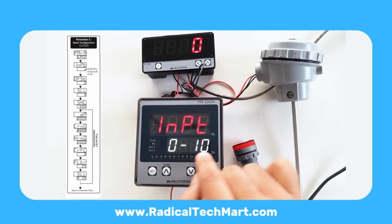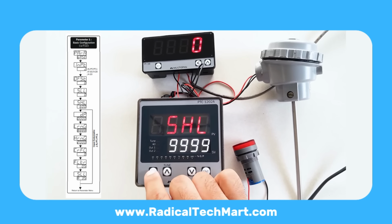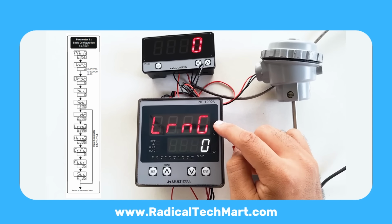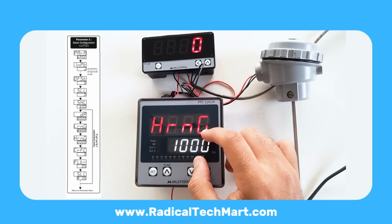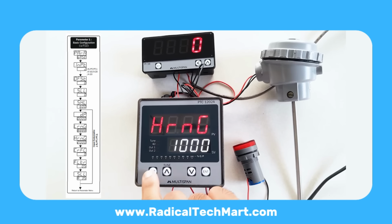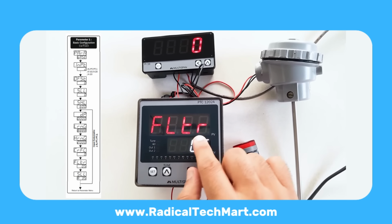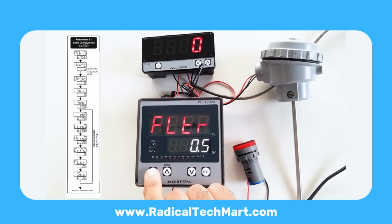For linear analog inputs, 0 to 10 volts, 4 to 20 mA, you'll also set decimal point. Low range value: what should the PV read at 0V or 4 mA? High range value: what should the PV read at 10V or 20 mA? Correction factor, offset with linearity, if needed. Filter time, default about 5s, set lower for faster updates, min 1s. Exit base to return to the main list.